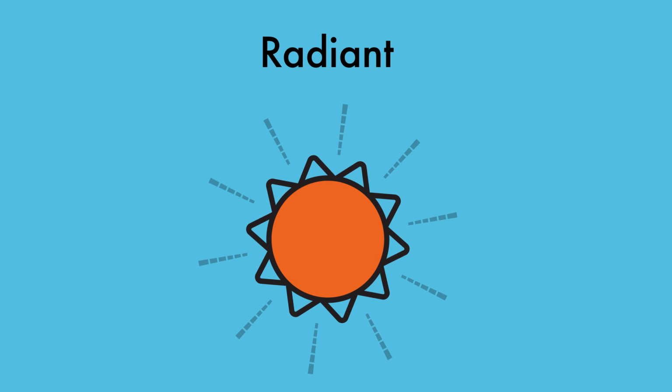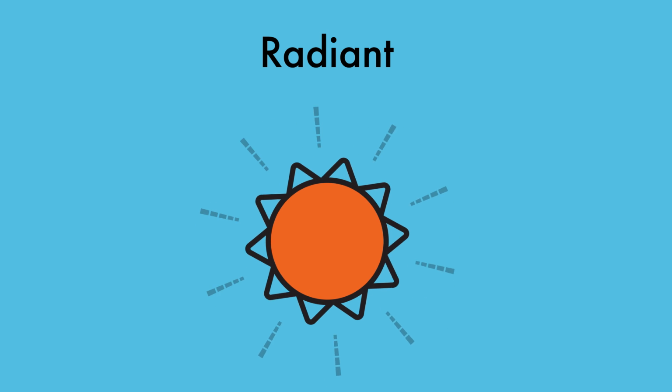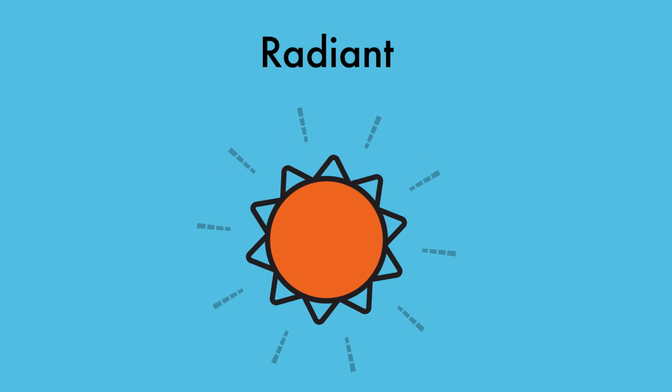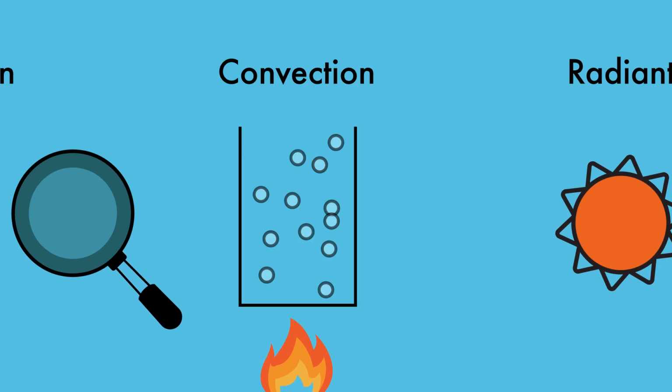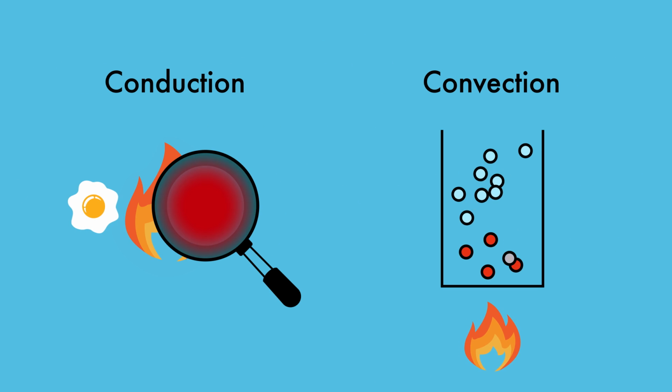So in a fluid bed roaster, the air is moving the coffee around. The air itself is hot. Those molecules of air are carrying the thermal energy to the coffee from the heating element, as opposed to the coffee collecting that from a drum wall or some other larger material. The third kind of heat transfer is radiant. It's a lot more difficult for us to measure and control in our roasting drums, and so we're really going to focus on convection and conduction.